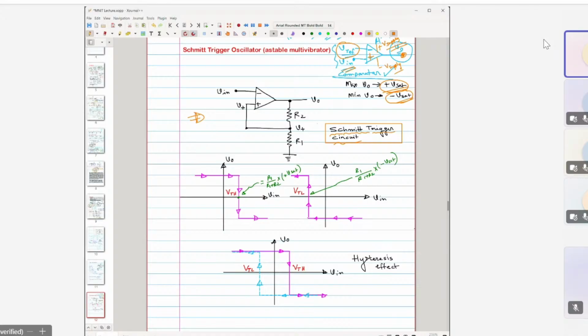Now here, one important thing is that from this output we have tapped, we have used two resistors connected in series, right? So basically V out would be dropped across this R2 and R1, and between them we have taken another tap. From this we have taken the feedback and fed it back to the non-inverting terminal of this op amp. So that means it is now in positive feedback, right? And here we are giving this input signal.